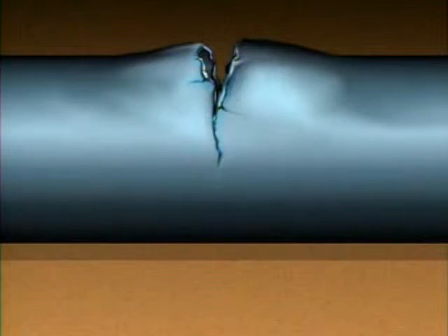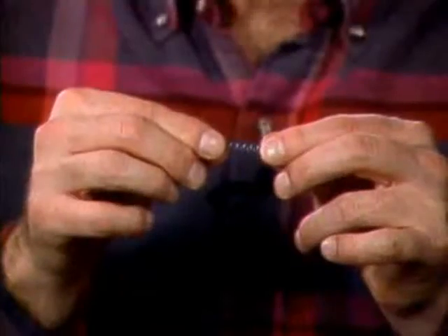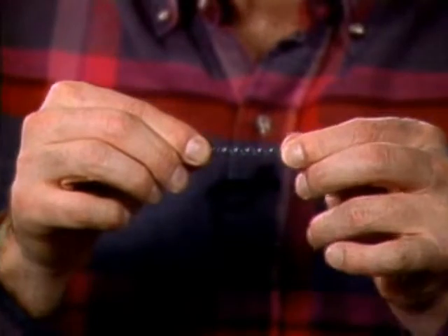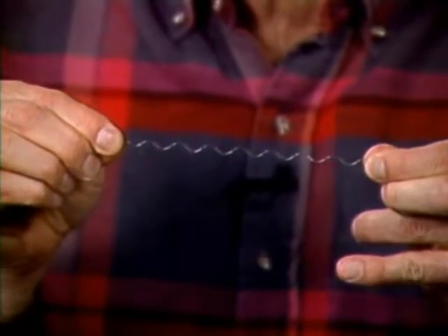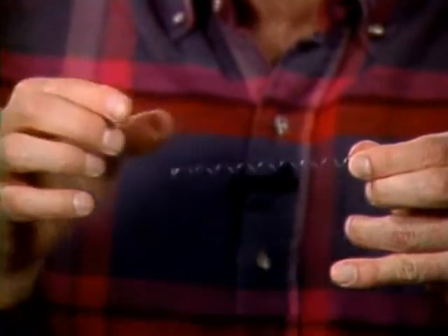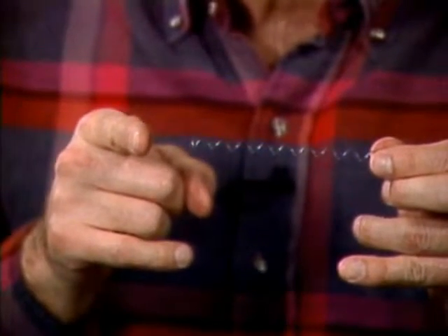If a pipe is overpressurized, the excessive stress may push the elasticity of the pipe beyond its limits. If the stress is great enough, the pipe could rupture. Solids that are highly elastic will generally yield to the deforming forces of stress. Steel, for example, can withstand a lot of stress before it loses its elastic properties. That is, before it reaches its elastic limit. The elastic limit is the point at which the force applied to a solid exceeds the ability of the solid to return to its original shape. It's the point at which the solid will remain deformed.